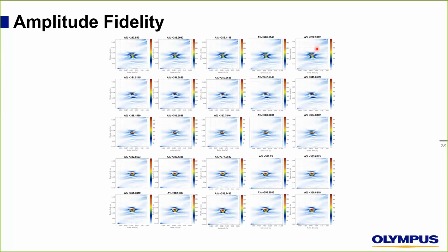So here, there is one question: how is the OmniScan X3 displaying the amplitude fidelity? The amplitude fidelity that is displayed in the OmniScan comes from which axis? We are actually taking the worst measurement, or if you like, the lowest amplitude fidelity, which means the highest value. So OmniScan is showing you the worst case of amplitude fidelity in all these axes.